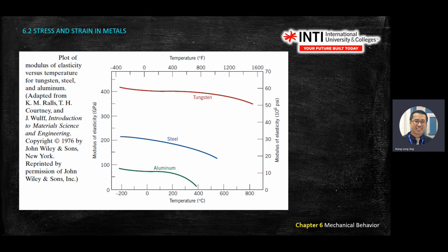So it depends on the question, what it asks you for. Of course, this will give you the dimensions of the thing. So let's say you have a 1 meter cross section, so A is 1. The force you have, and Young's modulus you have from the graph. I give you the original length as maybe 1 meter also. So you can find the change of length for aluminum and tungsten from the graph. Does it make sense to you? Right.